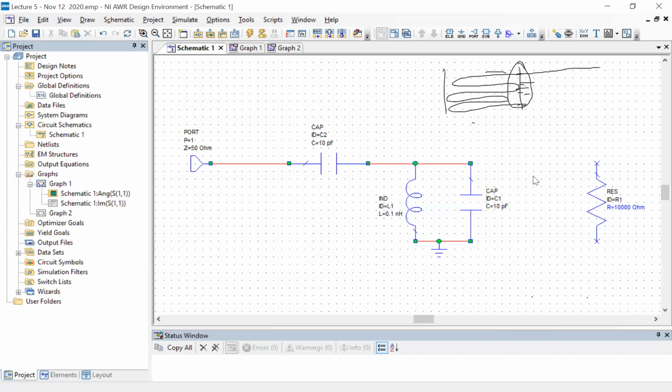Small question about the thing you were talking about before this. So we parameterized the resonator with the omega naught and the Z characteristic. Yes. And so I didn't really understand why we don't have control over the ZR and only the omega naught. Oh no, of course. You misheard what I was saying. Of course you have control over it. Omega naught and ZR are equivalent to defining a value of L and C.